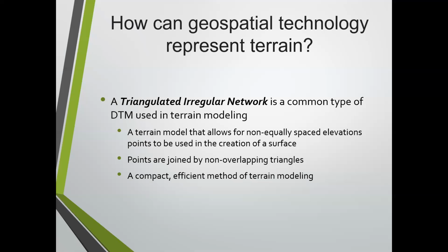Are a lot of you guys out there still using data collectors and all that? You can draw your break lines while you're out there, right? You guys are doing that? We do a lot of line work coding in the collector. As soon as you import it, it's a break line. Your curve line is an elevated break line. Center line is an elevated break line. The whole deal.